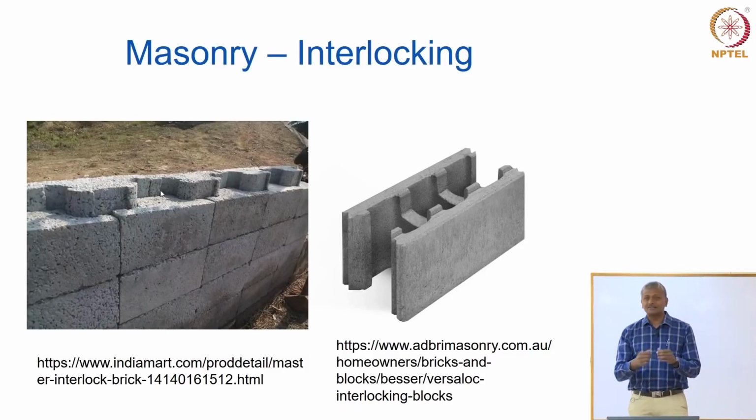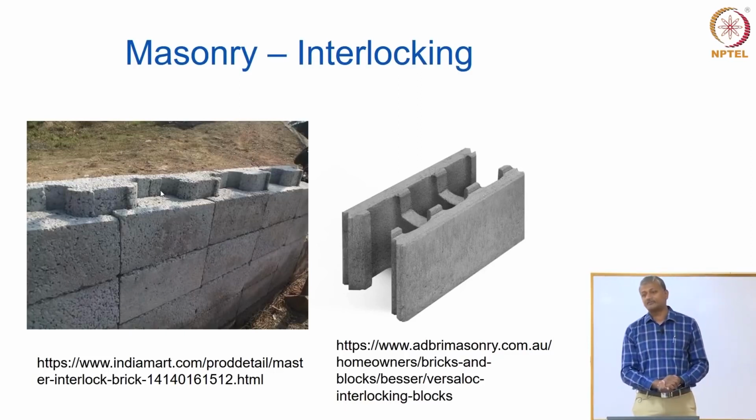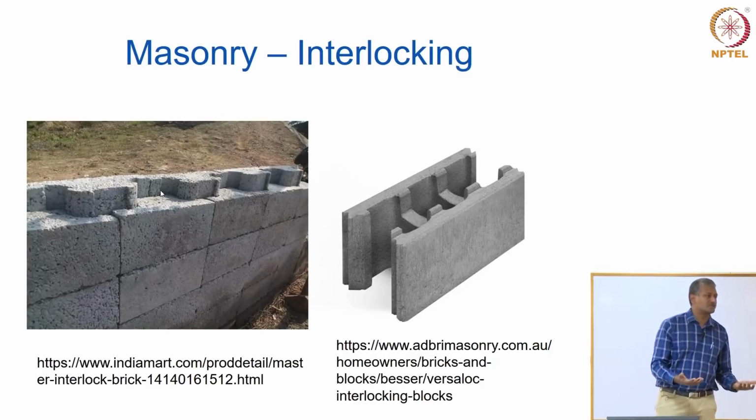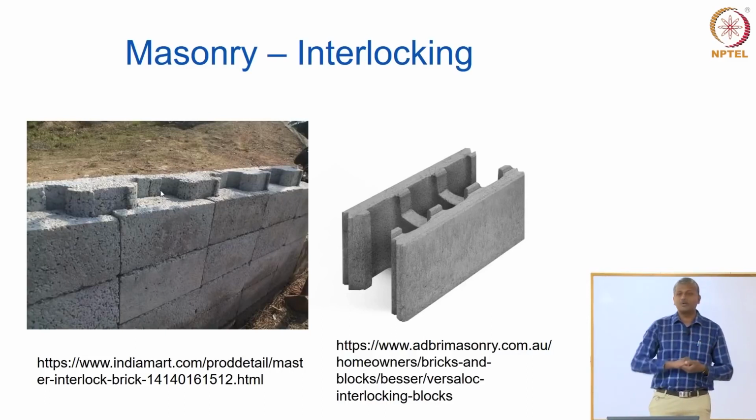So because of that, the use of mortar for joining the blocks is a process that actually slows down the construction work significantly, okay? If you really think about it, it slows down the construction work significantly. So the way around it is to ensure that you don't have to actually put any more mortar, but you can still get good stability by providing interlocking between your blocks.